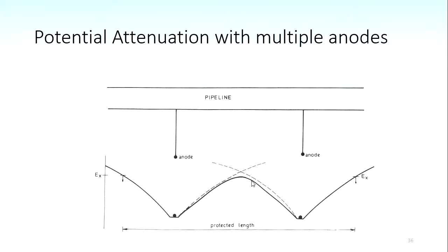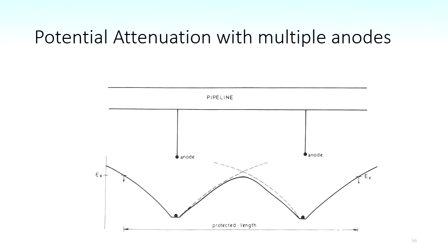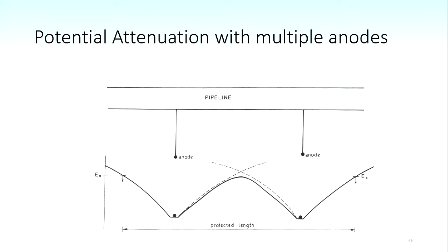This is also on the handout. This is what they call a close interval potential survey. So between the test points that you've got spaced out along the pipe at 1 kilometre gaps, you might want to start looking for defects over time, and that's what this gentleman's doing. What he's got is 2 ski sticks here, effectively, and each one of those has a reference electrode connected to it. And he's also got a couple of reels on the back of the carrier here, which allows him to connect to the test post.